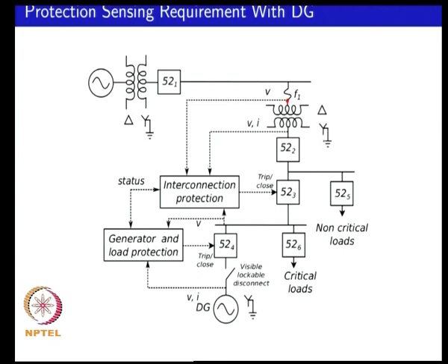You might have secondary side voltage measurement, and you might also have secondary side current measurement. With the voltage measurement you will be able to look at power quality: whether your voltage is in range, frequency is in range, whether there are distortions, etc. Once you have voltage and current, you can then measure power, and whether power is flowing in or back out into the system.